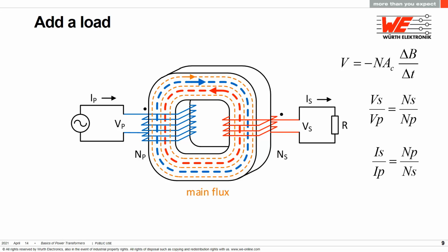The interesting thing about a transformer is this. When we design a transformer, we determine a maximum operating flux based on volt-seconds, not current. We want the magnetizing current to be small, but current creates flux, and by loading the transformer, we increase this flux, often more than tenfold. This flux could easily saturate the core if it were not for the fact that the flux created by the primary and secondary windings are opposite, and they cancel each other, leaving us with the net flux of the magnetizing current. That's what the blue, red, and orange arrows are trying to illustrate.